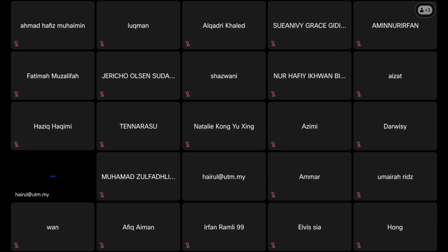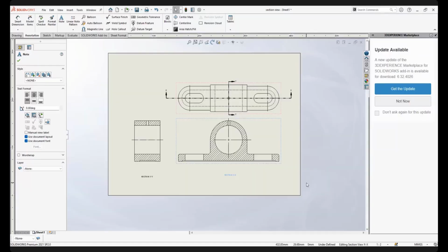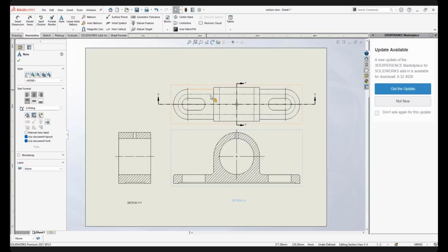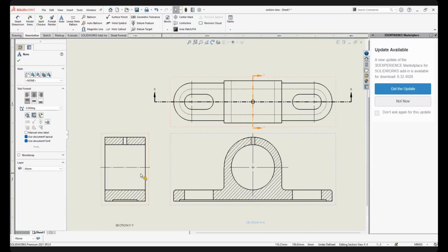This is what it looks like. This will be your answer in your drawing. This is the side left view of the front view, not the left view on the plan. Even though the cutting plane is on the top, you represent it on the left view of the front view. Clear? This is the orientation of it. That's how you do it.